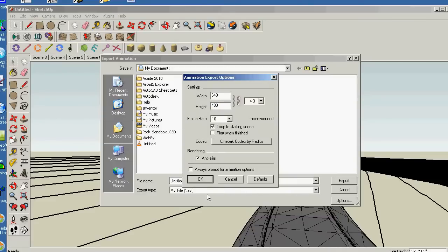I'm going to stop this just before I hit OK here, because it'll probably take down the machine. That is, in fact, how you go about doing a simple fly-through animation. And then the next bits, of course, are using those point files to stack cars and pedestrians and the like. Once again, all you need is sets of X, Y, and Z point files for the paths of where you want things, and then some sort of concept of time step analysis.